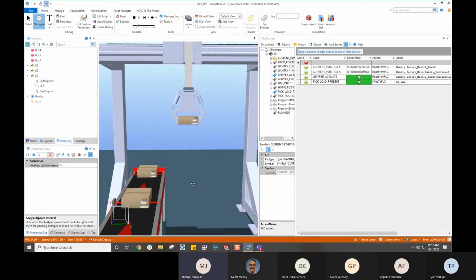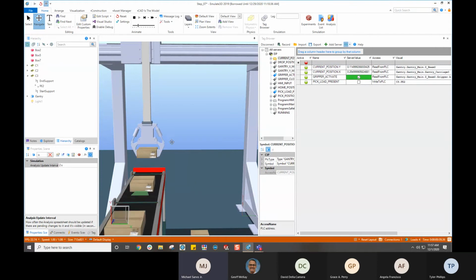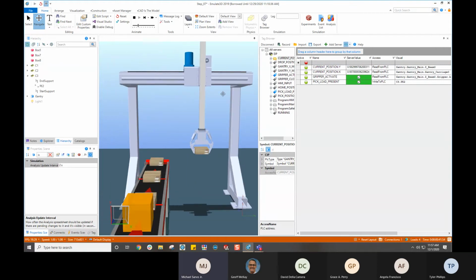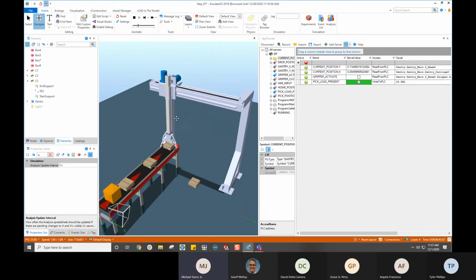All right, so I'm just tapping on my HMI screen now, the real hardware HMI. Open the gripper, close the gripper, and so on. I'll put it back and run, and now it'll go back to running again. So this is a real PLC controlling virtual machinery and interfacing with not just the machinery that's in the scope of my control logic, but I'm interfacing with a simulated conveyor.